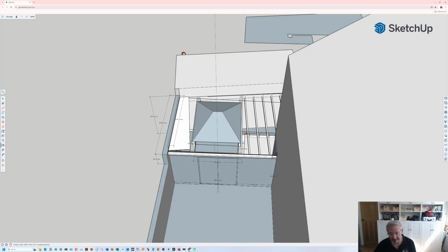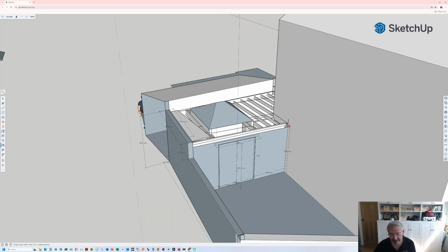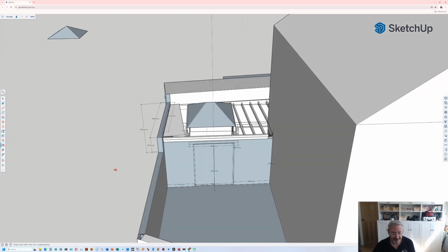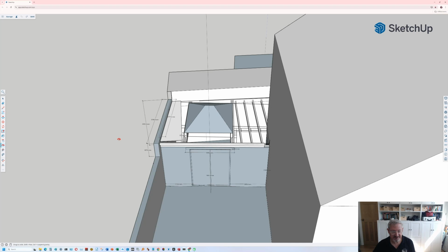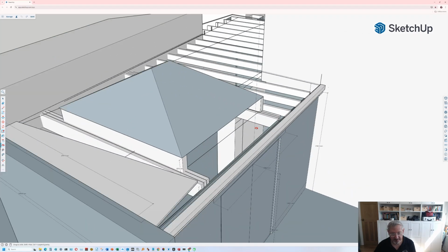The existing wall is going to come down a little bit. We're going to build this wall to be 2180, so about 8 foot high, 7-8 foot high. And the existing wall will come down to that height to give an extra bit of support, especially on this beam here. So we're going to have a triple beam of, I don't know quite what that ended up being. Let me just measure it.